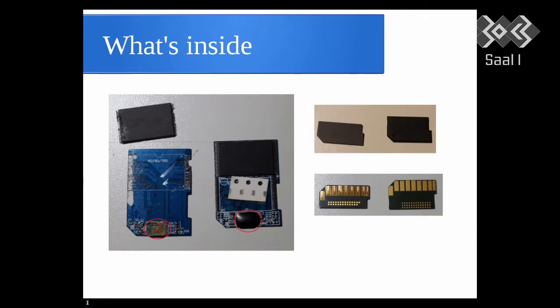This is what's on the inside. So there are generally a couple of broad categories of SD card construction we found. On the left is what we call a discrete construction. They have a standard TSOP flash memory that's soldered onto the board. We show it removed on the left, and the little spot where you see the red circle is where the microcontroller is, a chip on board with a glob of epoxy on top. So if you knock off the epoxy, you can see the chip beneath it.